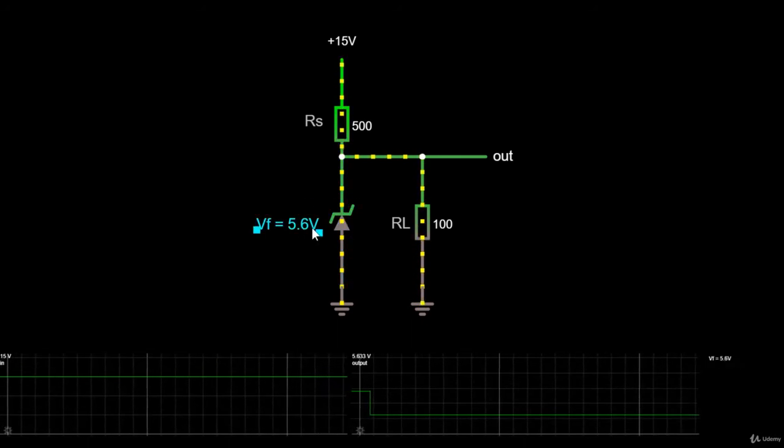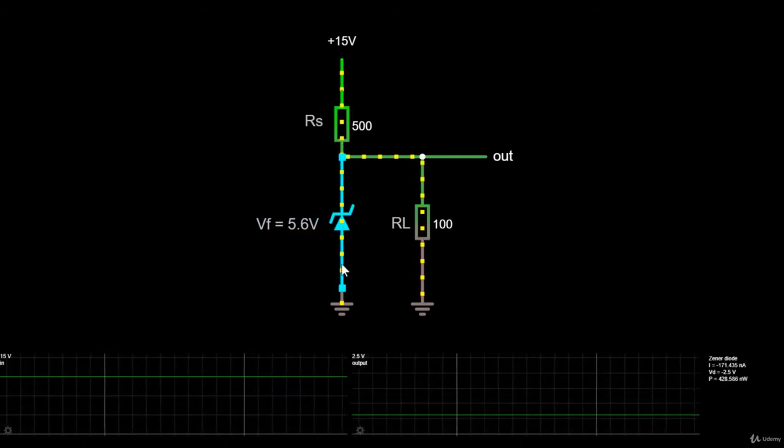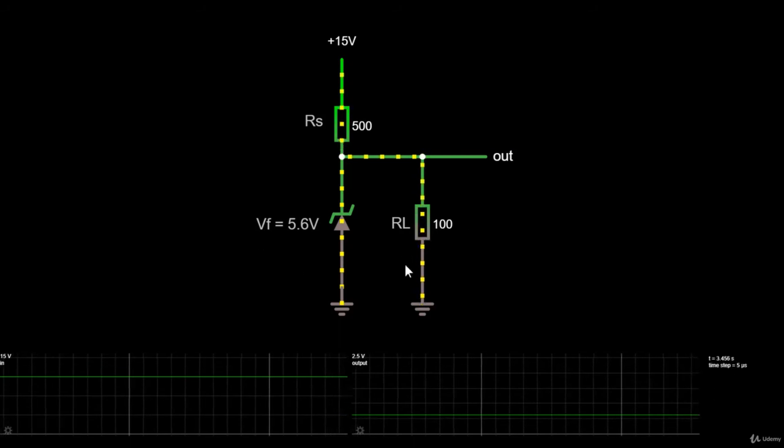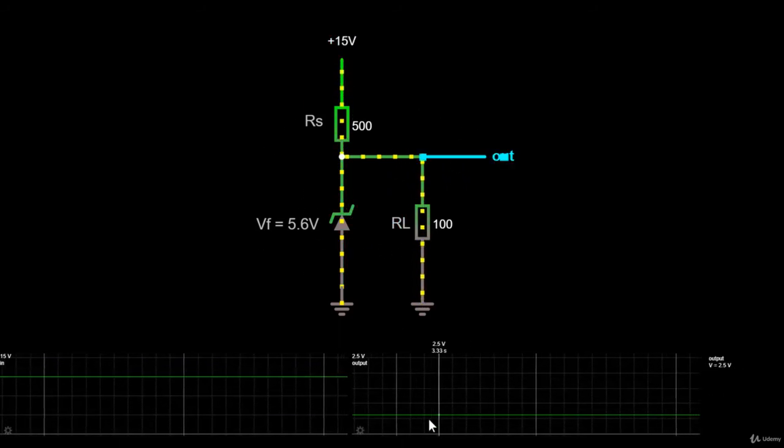As I said, the Zener diode needs a minimum current through it to operate well, and this time the load resistance steals the current from the Zener diode because the current is always following the path of least resistance. So in order to solve this problem, and also the other problem with the noise added on top of the DC voltage, here is the following circuit.